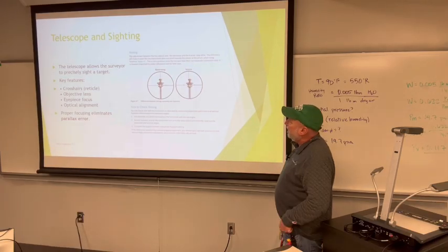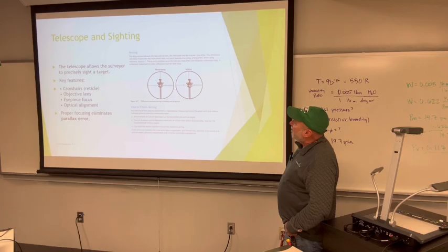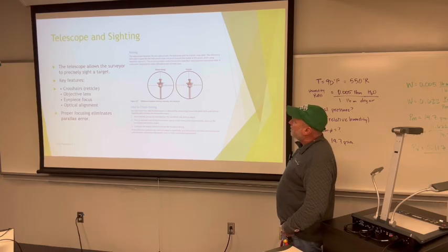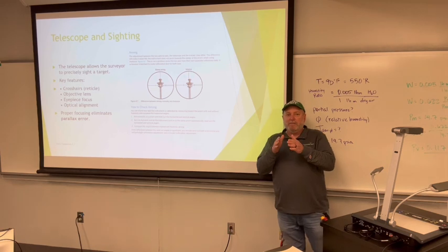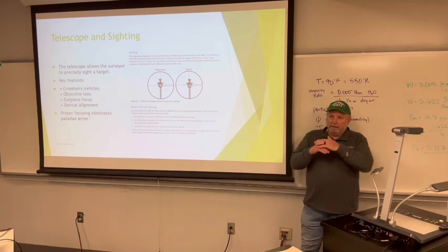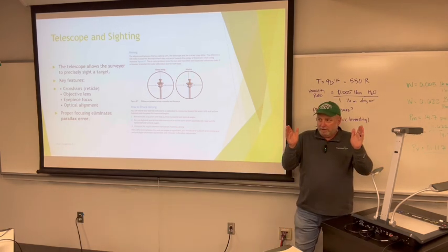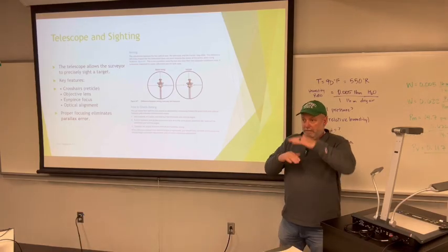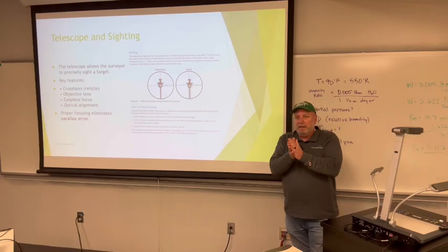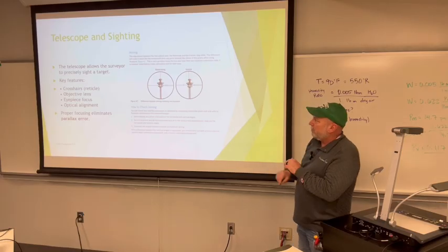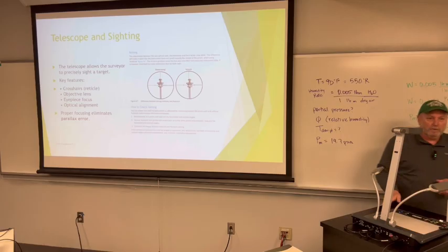I do believe here it also says that it's not a problem since the two axes have their own separate collimation data. It is, however, important to make sure to do the collimation test for both axes. So it kind of knows that, hey, I'm snapping to this, but I know I'm going to be off so much this way, so much that way. If it gets off way too much, you need to do a collimation adjustment to get that minimized. But apparently, per Trimble, that's okay, not the end of the world.